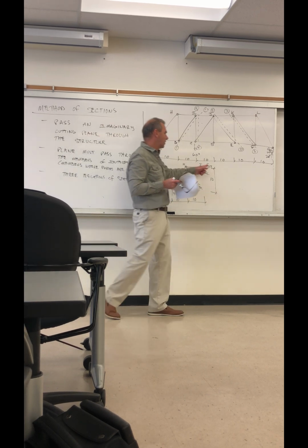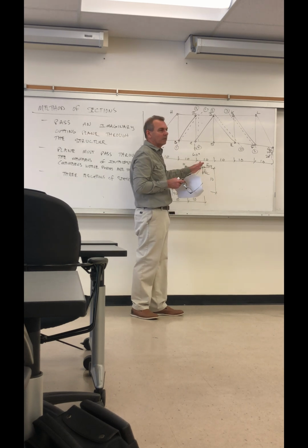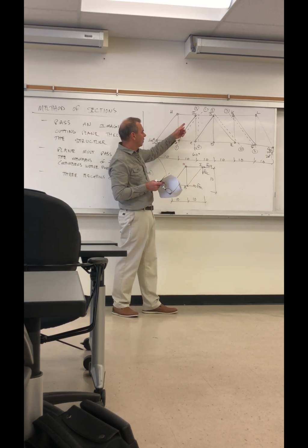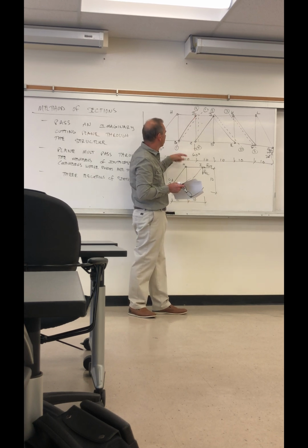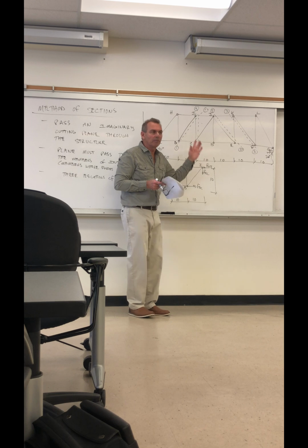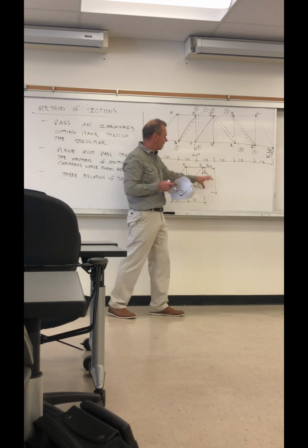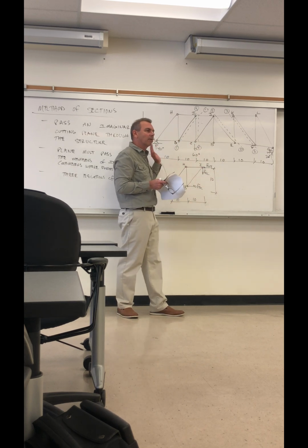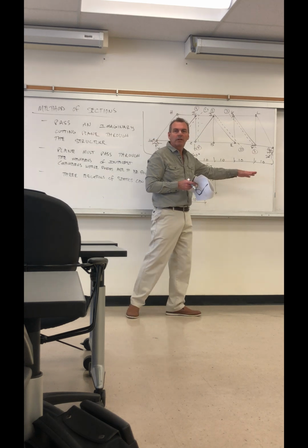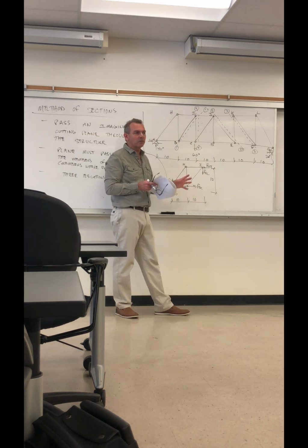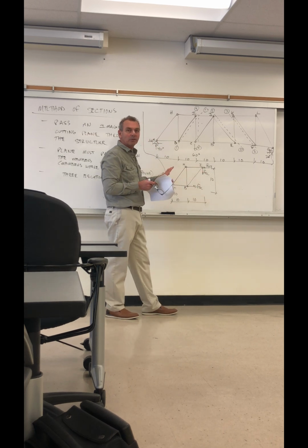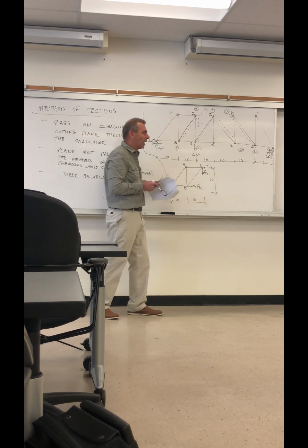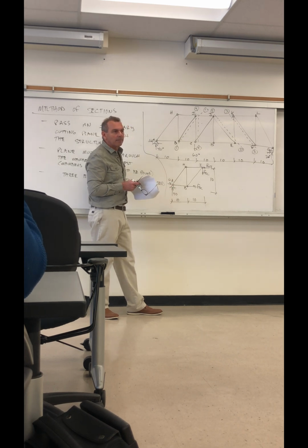And these forces represent the ones that were actually cut through, for section 1-1. We didn't cut through any other members. So those three forces represent the behavior of the rest of the structure. You don't need to include the rest of the structure for the statics, but on the left, you have to show the whole structure, including any applied forces and reactions as indicated there.